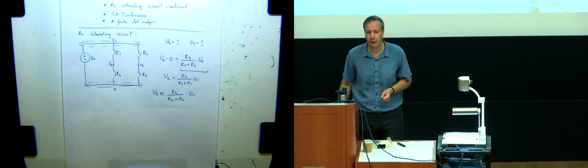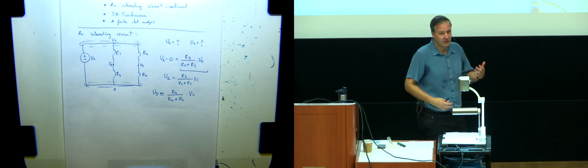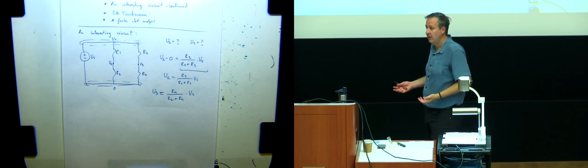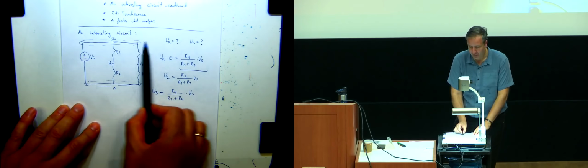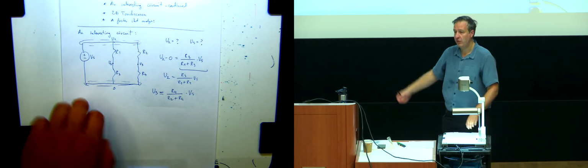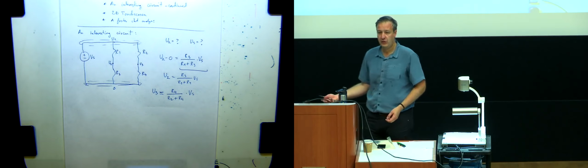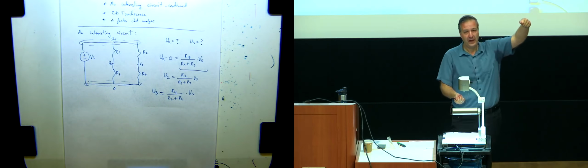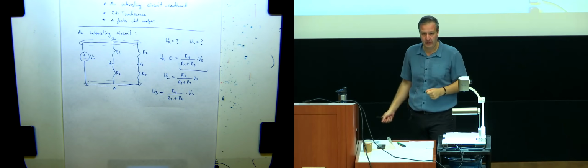It's a single node. So in terms of voltage across them, these two branches are completely independent. I could keep adding branches like this, and the middle potentials at each one of them could be separately calculated as voltage dividers. Does that make sense? Because it's always Vs applied to each one of these new things that come in.